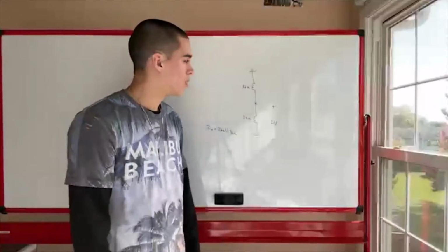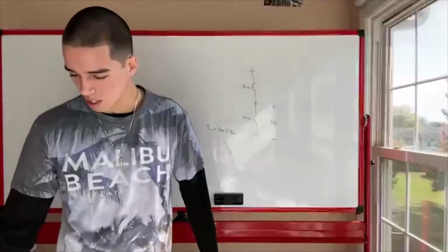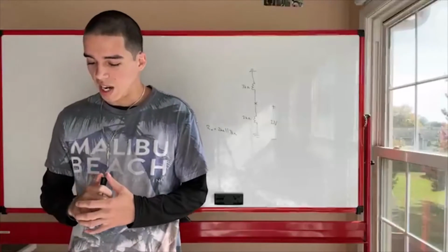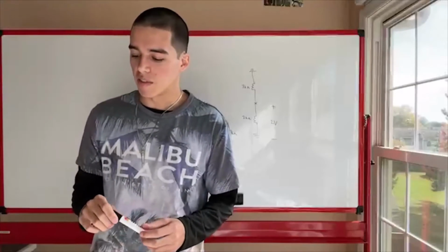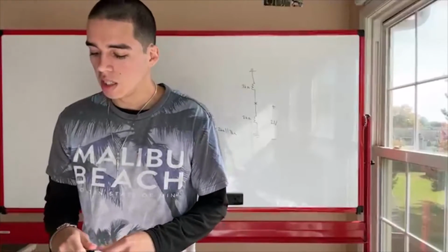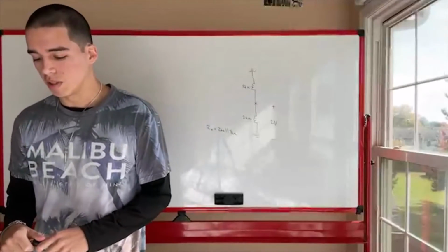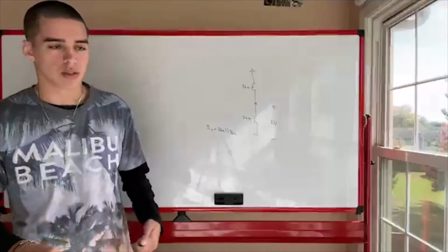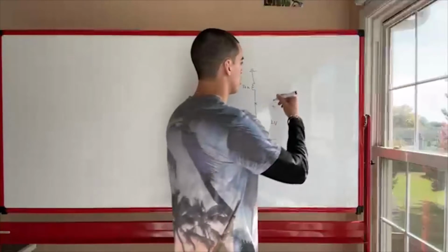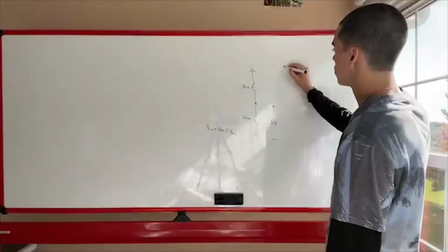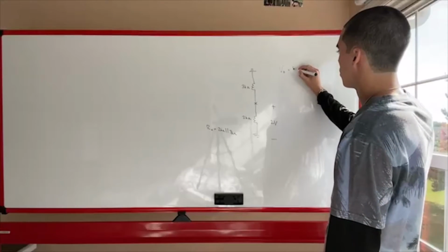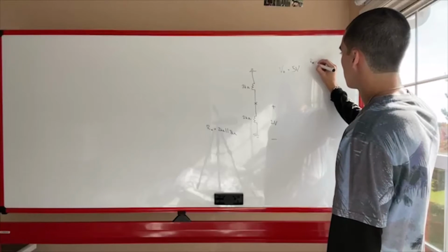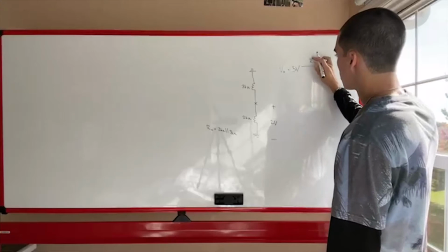There you go. Oh wait, there's more to this question. If the resistors used are not ideal but have a plus or minus 5% manufacturing tolerance, what are the extreme output voltages and resistances that can result? Alright, so let's set up the equation for the output voltage. VO, that's just a voltage division. So you have your 5 volt source multiplied by R2 over R1 plus R2.